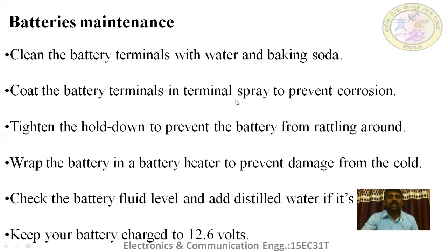Coat the battery terminals in terminal spray to prevent corrosion. So there are so many coatings. Even gel type material is used to coat the terminals to avoid corrosion. Tighten the hold down to prevent the battery from rattling or vibrations. Loose connections may discharge the battery soon, and also cause heat at the battery.